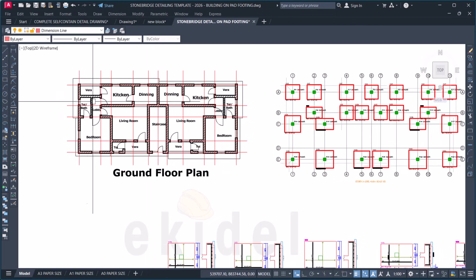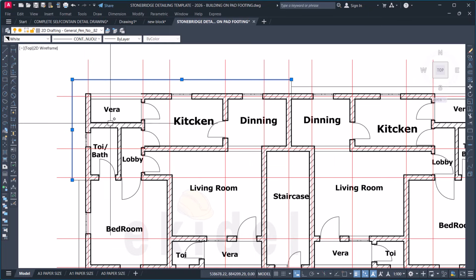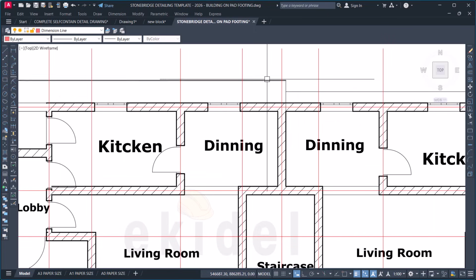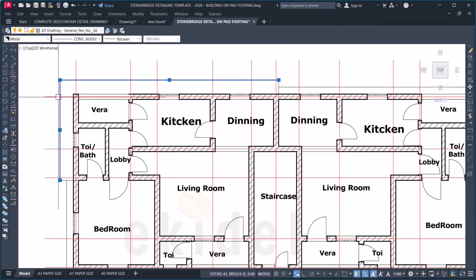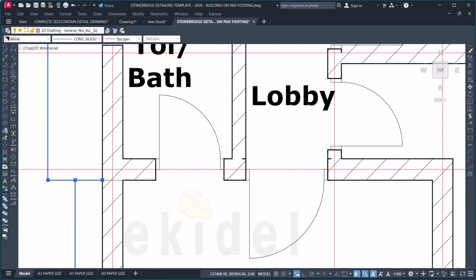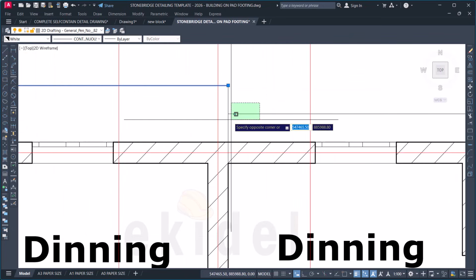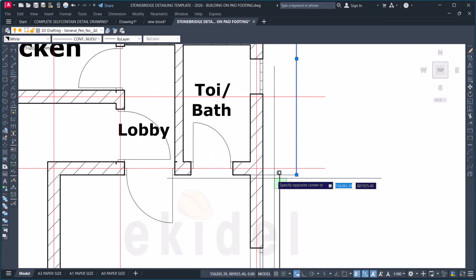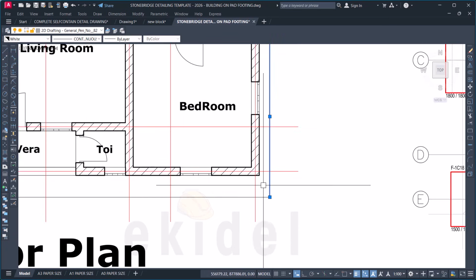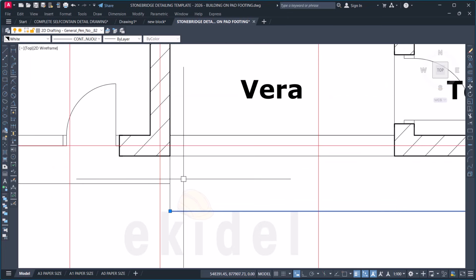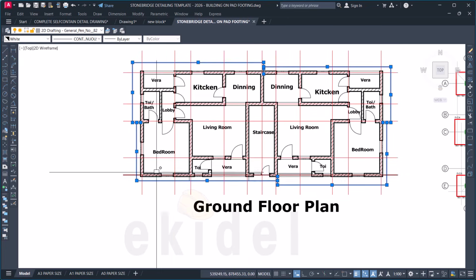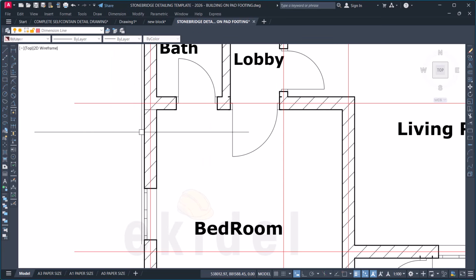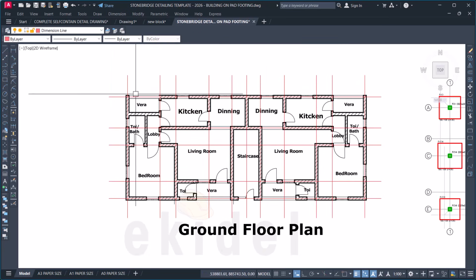So what I will do now, these things you're seeing here are cantilever lines, and cantilevers are above the foundation level, which is at around 3 meters level or something like that. So in this case, I don't want to deal with cantilevers, so you have to remove anything that has to do with cantilevers, because we are not dealing with cantilevers at this level. We are only dealing with the part of the building that has direct interface with the soil or ground directly, because we want to prepare our foundation trenches. So I'll just remove all these now that are not necessary. Okay, that is fine. So once I do that, I'll now press E, enter, and that will take off all the cantilever lines.